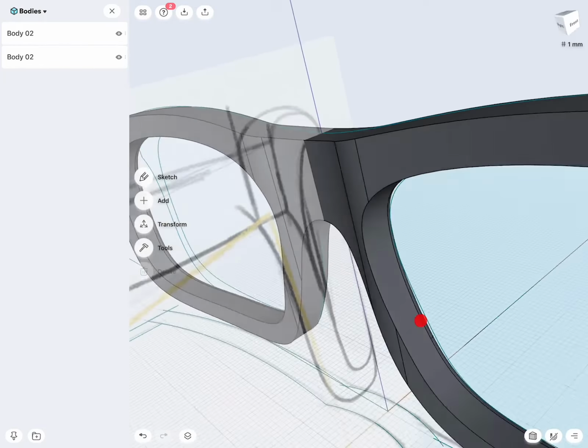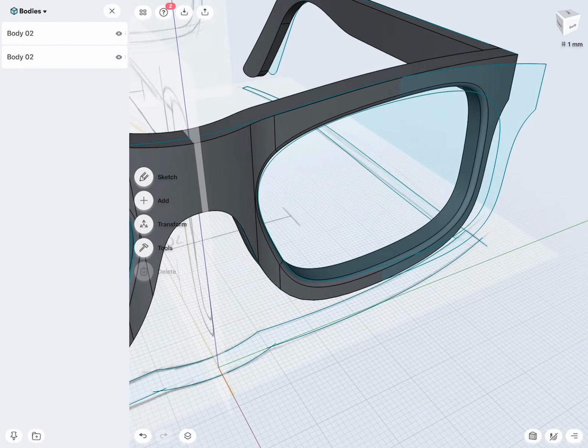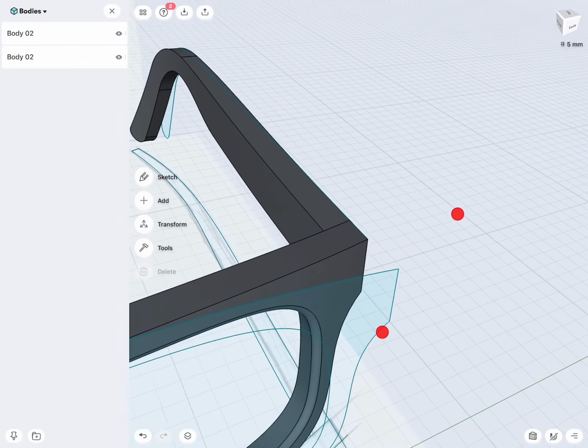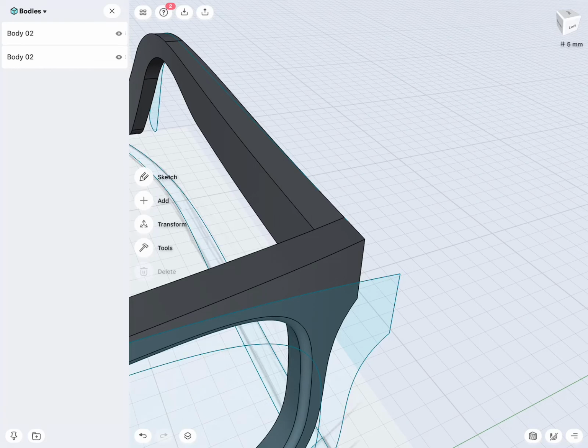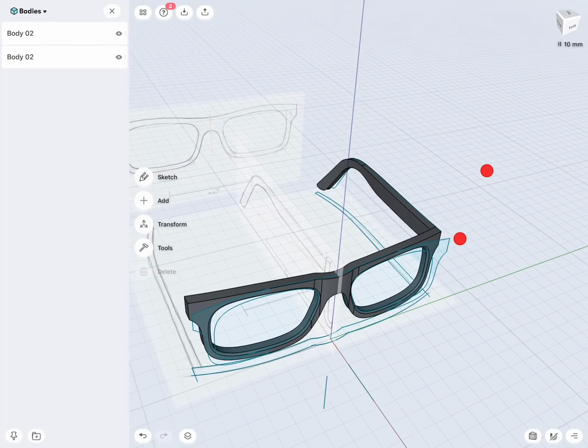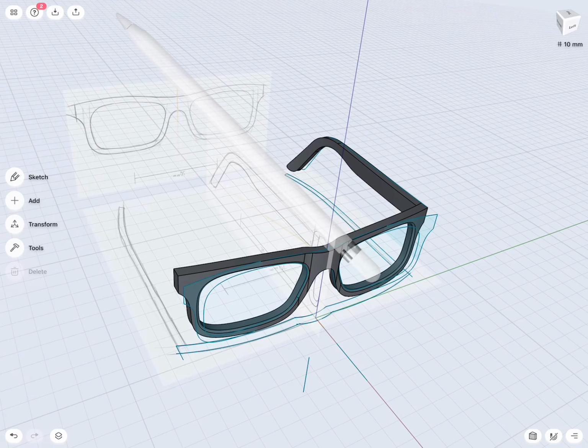I added some fillets here before. I highly suggest to not do any fillets at this point. We will continue working, and then when we're done, then we add all the fillets. The main reason for that is fillets are more a decorative element, and in all CAD programs, fillets can slow down your design. The more fillets you have, the more it will take to process everything.